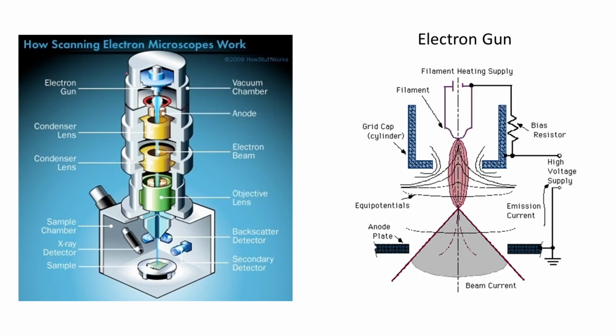So in SEM, firstly, I have told you that it is the vertical optics. It is not a horizontal one. So you have your specimen over here, and your optical axis is this one, which I will be drawing right now using my red pen. So this is your optic axis. So firstly we have this electron gun. Electron gun produces the electrons by heating or by thermionic emission or by field emission, Schottky emission. There are different sources for the electron gun.